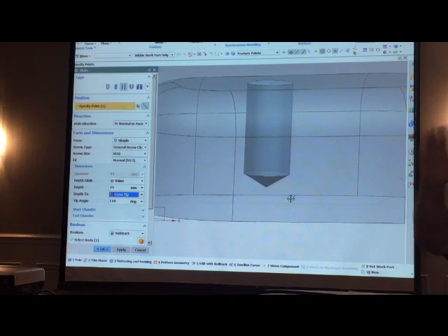Now, you haven't changed what the manufacturing guy gets. He's now going to be told this value when you run your annotation, because all we've done is change how you input the information. The definition of the hole hasn't changed at all. It's a screwy number now because of the trigging out of that 118 degrees, but that's the value that'll be given to the manufacturing engineer. If I do an annotation call-out on this hole, that's what he's going to get, the height of the sidewall, even though I have defined it to the tip.